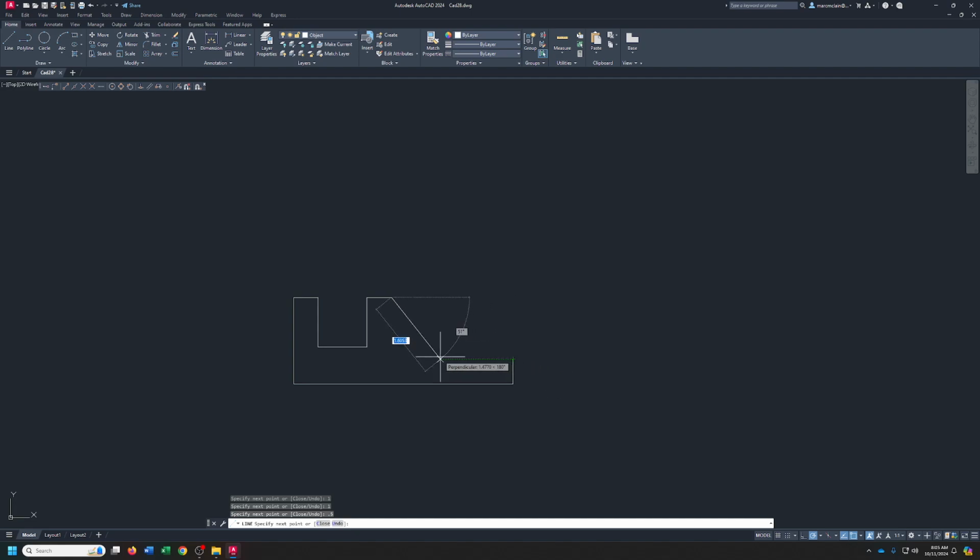Now I'm going to touch this, but I'm not going to click it, and then drag it back and keep that line green until it snaps vertical. Once it does that, go ahead and click, and then go back to that corner. There you go. Now, all that's left is your fillet in here, so we'll use the fillet command, right-click, radius, and that's going to be 0.25, according to the book.